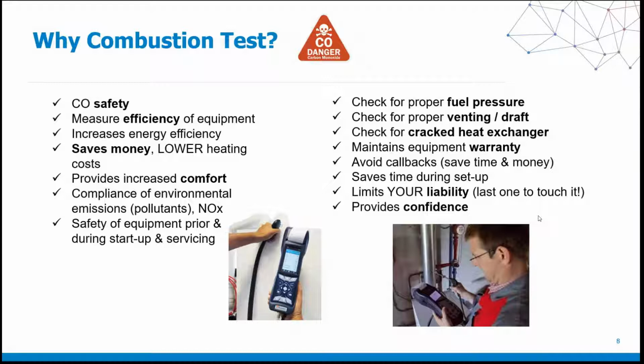We want to make sure that we're complying with the emissions regulations, make sure there's proper safety of the piece of equipment prior, during, and while servicing. We want to check the fuel pressure, check for cracked heat exchangers and the like. And also, again, it all ties back to limiting your liability. Those are the foundational reasons why we should test.